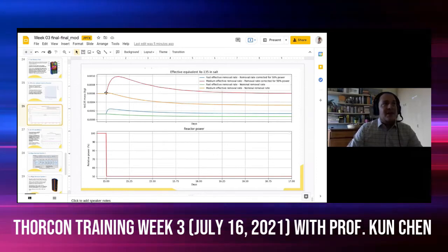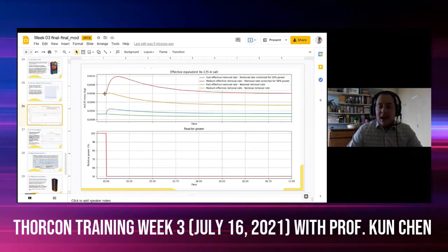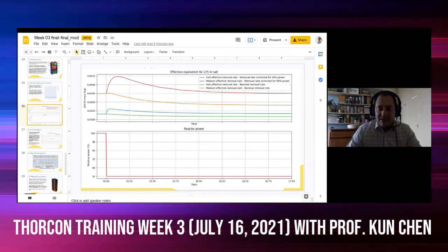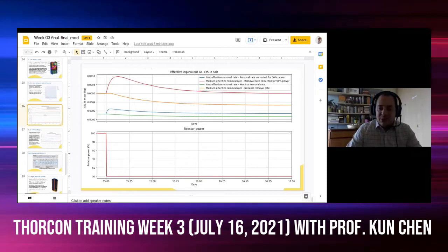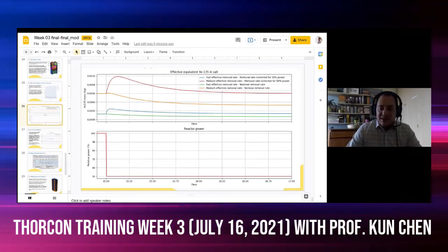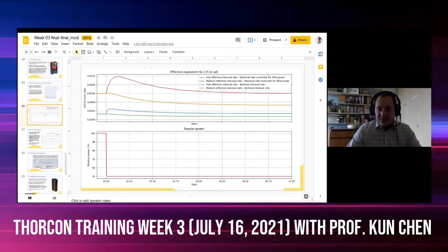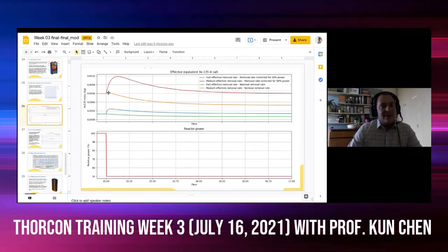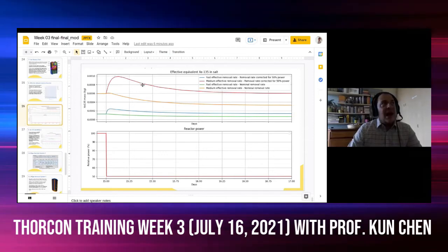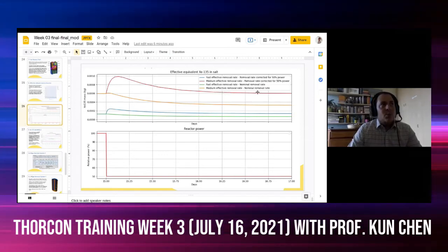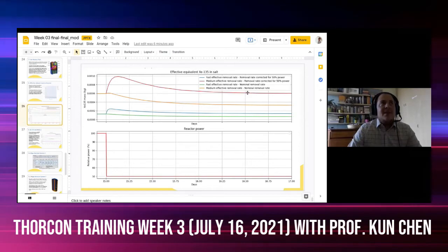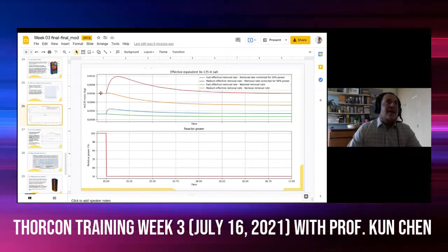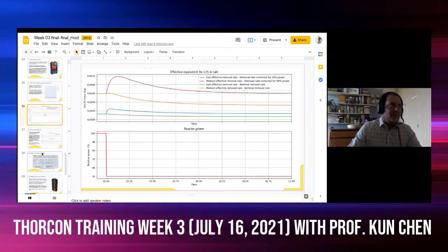On the other hand, if we adapt our removal rate, so in simplifying terms, the amount of salt flow that is flown in the header tank or exposed to the salt to gas interface, if we halve it effectively, after we reach equilibrium, we will go back to the same xenon equilibrium concentration that we had before the change in power.